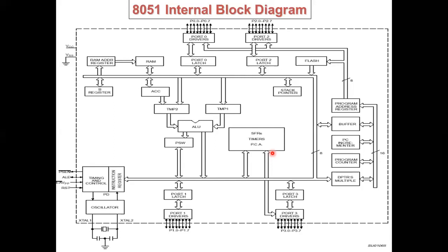For example, MOV A, B means we are putting only the opcode for the move. It is a 1-byte instruction. Here for MOV A, R0, they are using the R0 to R7 registers. If it is MOV A, R0, you have to put the address for R0. That is the concept in the 8051.